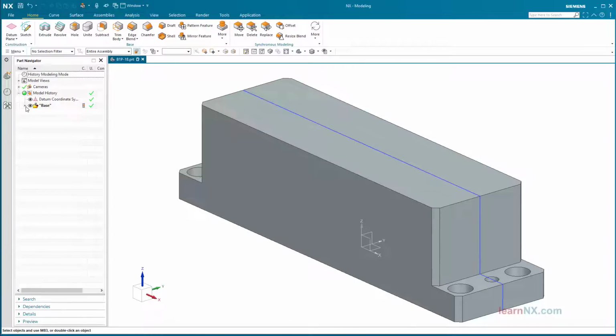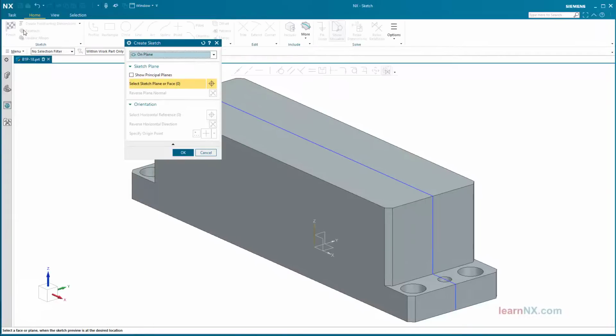Receivings. Now the 4 identical receivings are to be constructed. Of course, only one receiving is constructed, and this is then copied to the target positions. The position points are defined by sketch points and the orientations by coordinate systems. This way, each copy can later have a variational position and orientation. Determine positions. Create a sketch on the surface and dimension the 2 points.